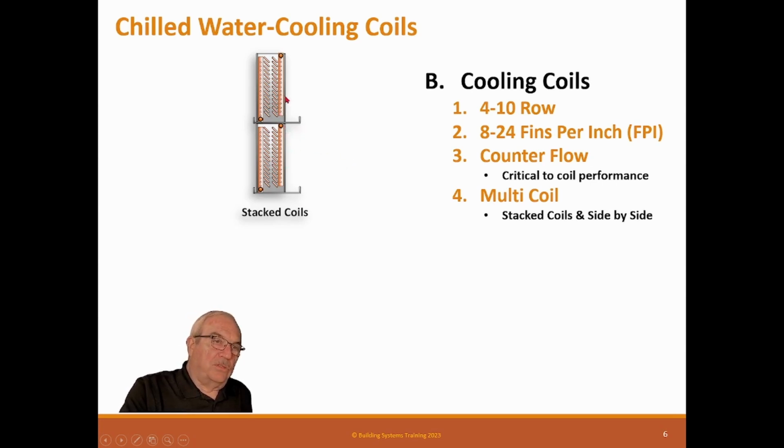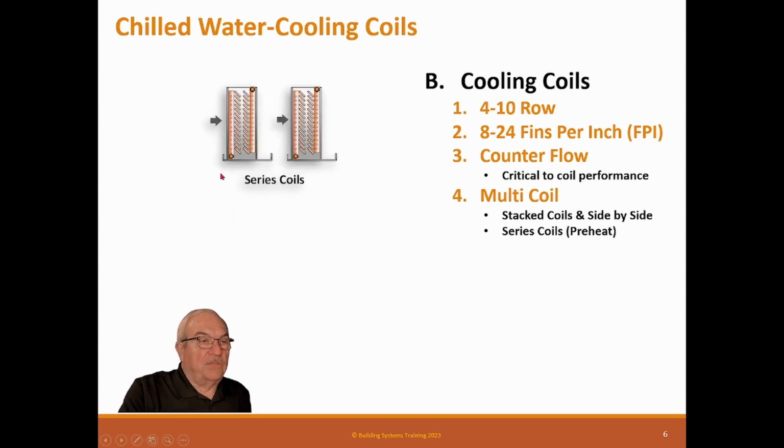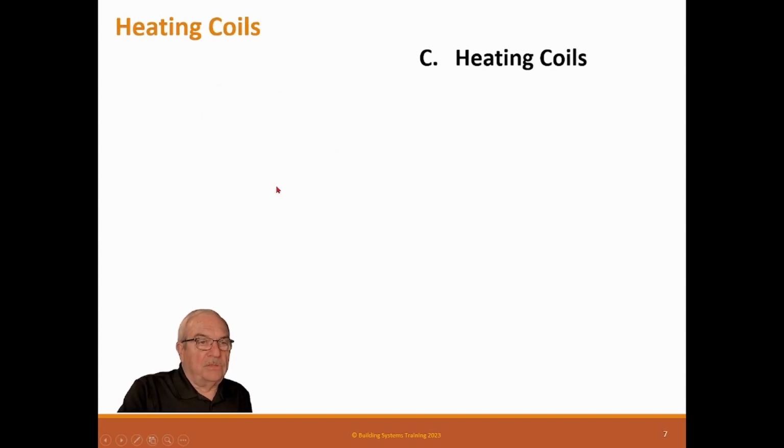So you wouldn't want this cooling coil condensate flowing down this coil. So you would want them to have their own pans. You can have series coils. Now, why would you have a series coil? Well, if you had an industrial process or something where you had a huge delta T, more than a 10-row coil or an 8-row coil would handle, so you put 2 coils in series. It's not really impossible to do, but you can do that.